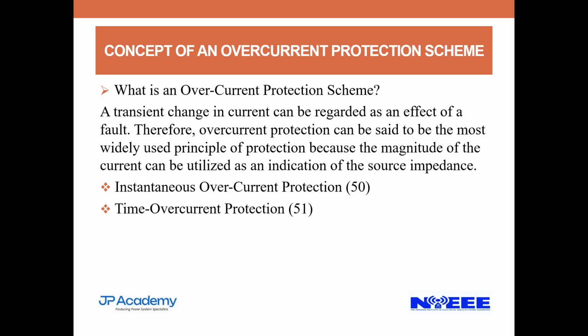And as the name implies, instantaneous. That's the difference between both of them. Instantaneous is as soon as there's a fault, the relay should operate. Time overcurrent is: there's a fault, there should be a time difference between the relays.